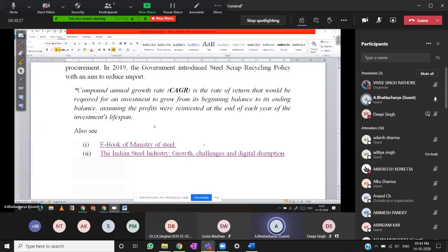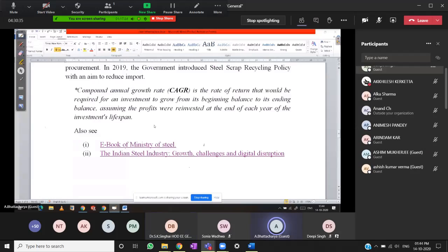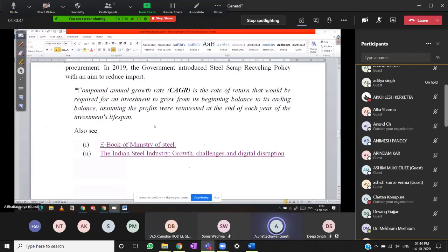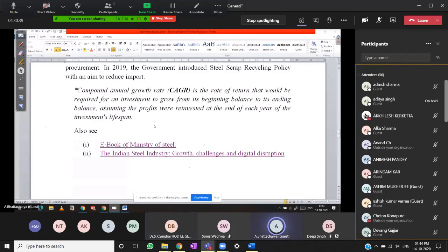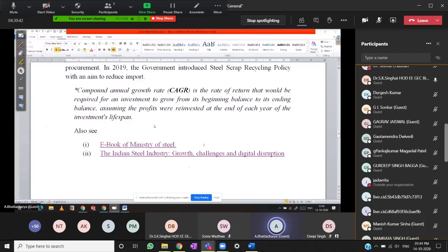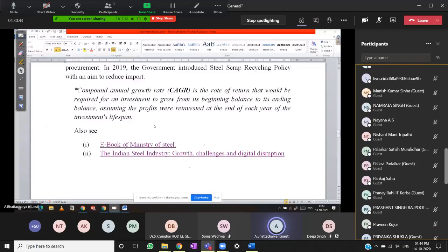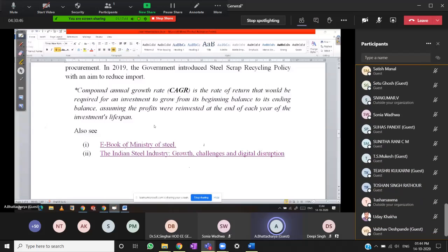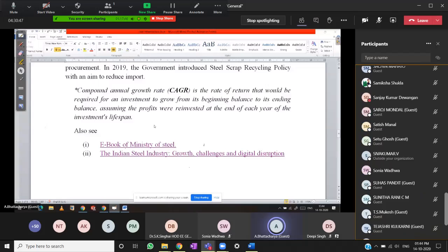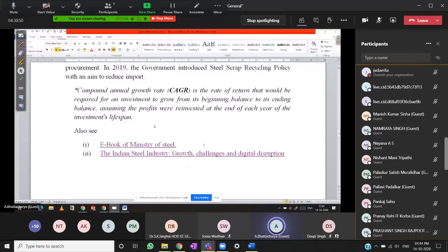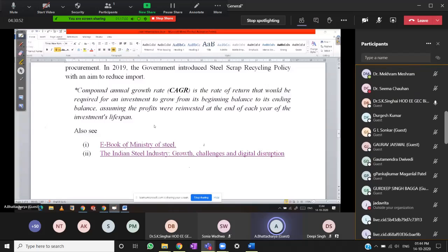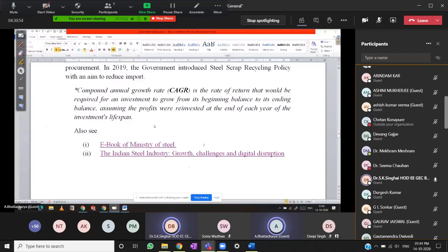For example, in hot strip mill, the minimum thickness rolled is around 6 millimeter. In cold rolling mill, you can go up to 0.6 mm also. So they have their own uses. The tin plate is made by cold rolling, because that thickness cannot be made by hot rolling.